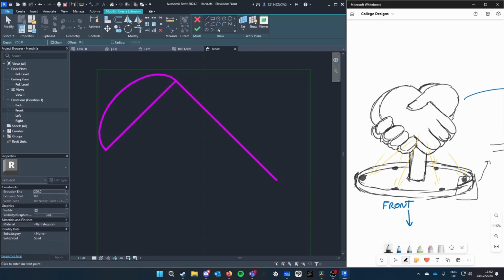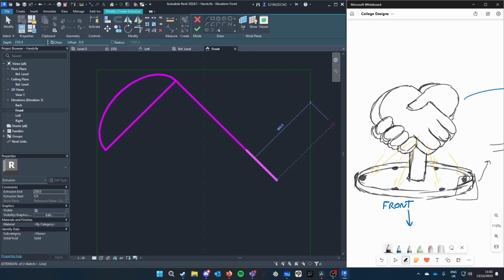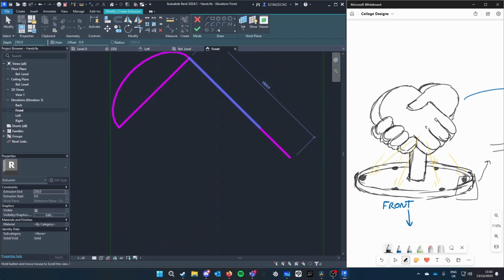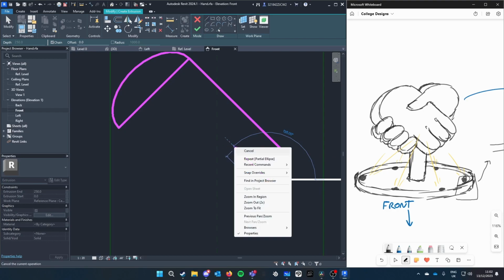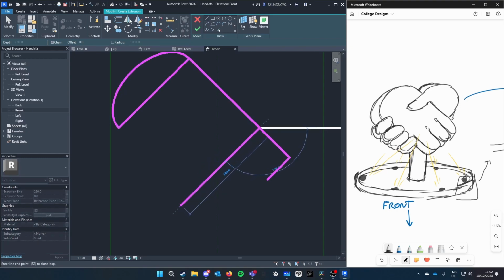Another tip is I've made this to be 700 wide. And because I'm using 3 fingers, I'm just going to say there's a gap of 20 mil between each finger, just so you can get the definition. So 700 minus 40 gives me 660, 3 fingers, that's about 220 mil per finger. Just so you don't have to faff around with anything. Right now I'm just going to put them as cubes so it's easier to see, and after I'll do whatever else. I can delete the lines later, they don't have to stay.